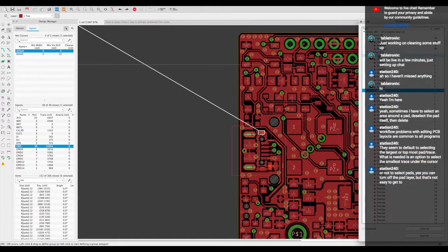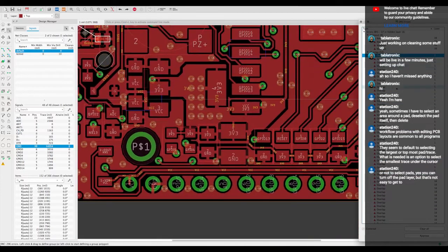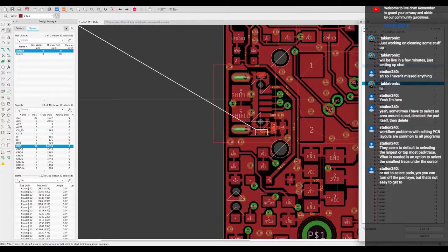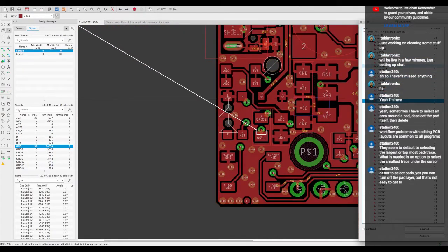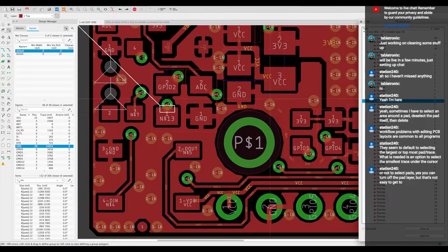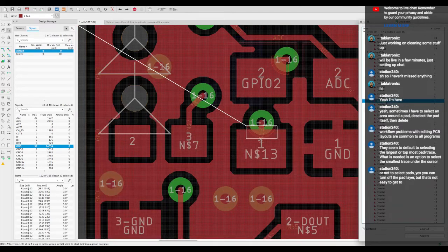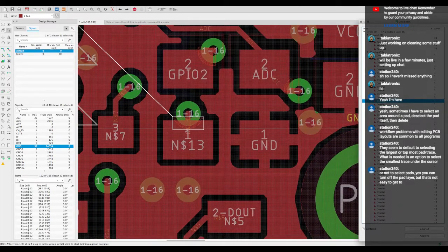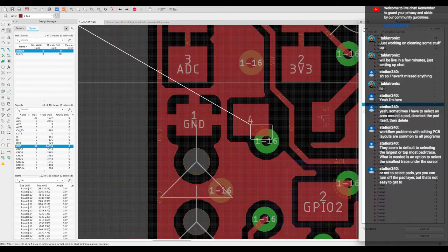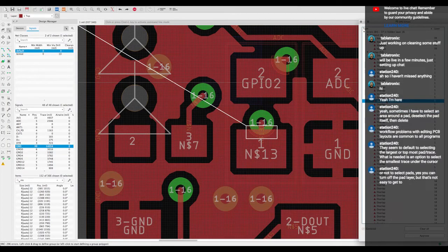I'll check it again. See, that's another thing when you have vias on pad, or via in pad, or via next to pad. I don't need to know about this overlap because it's the same signal, you know? So I could easily go down this whole row if they saw that they're all the same signal overlaps. Then, one sec.